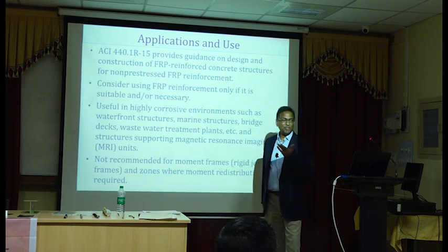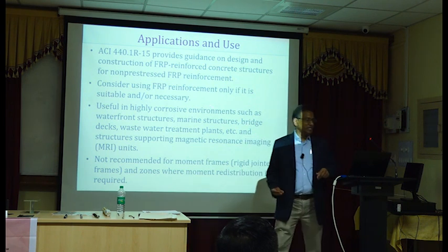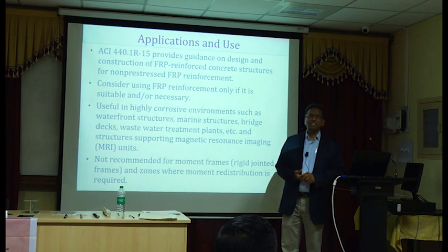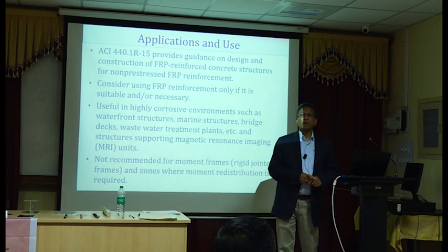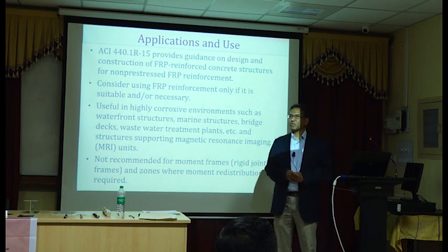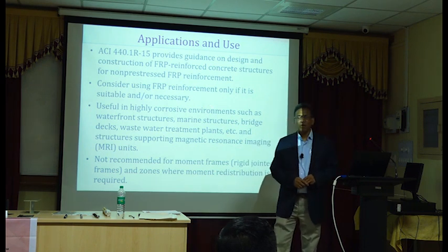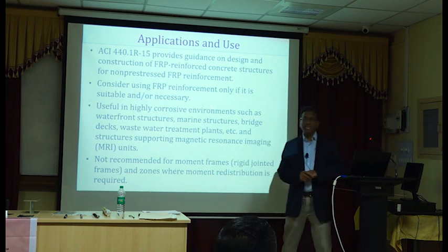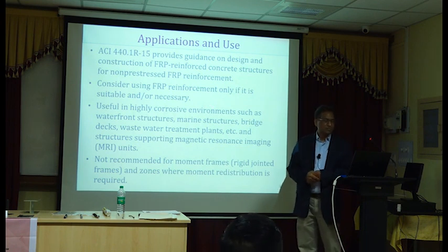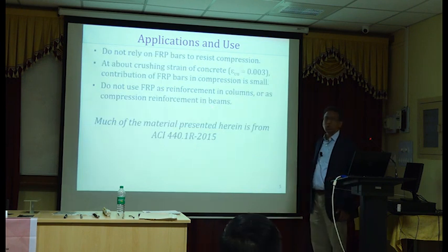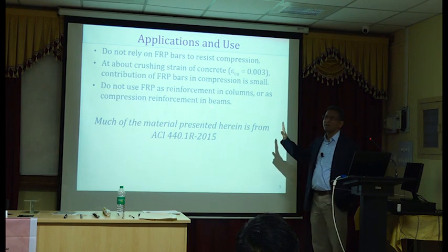I am really not surprised, but it's interesting that many of you are using 30% redistribution. It's really nice. But for steel reinforcing bars, 30% will work, no problem. At least 30% is allowed. European codes are all using 30% as maximum. ACI doesn't allow 30%. Okay, so FRP is a no for moment redistribution.